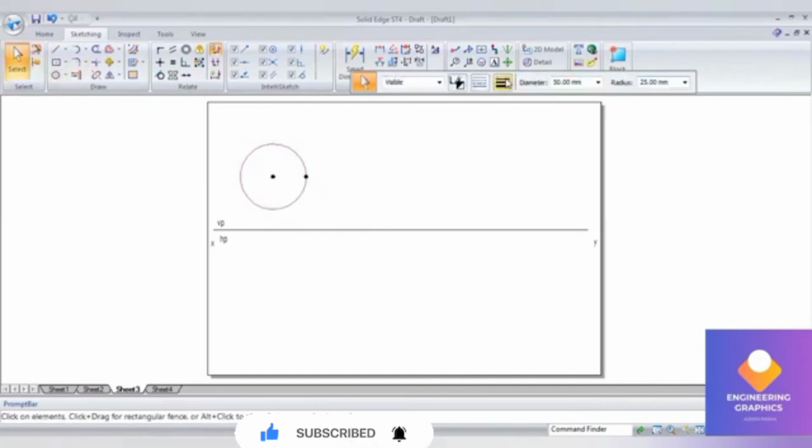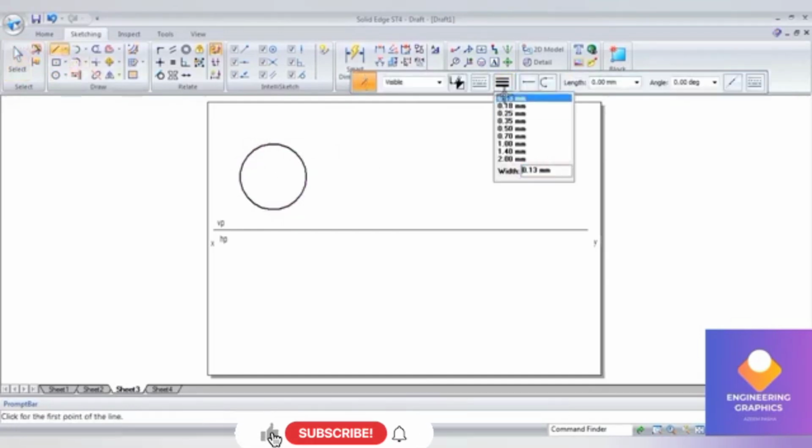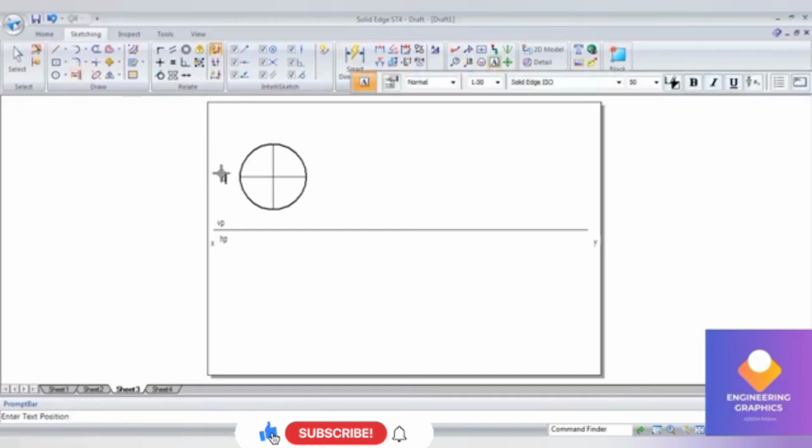Now I am going to divide this circle into 4 equal parts. Now write down the namings for it. Write A dash, B dash, C dash and D dash. Now project it downward to complete the first position top view.